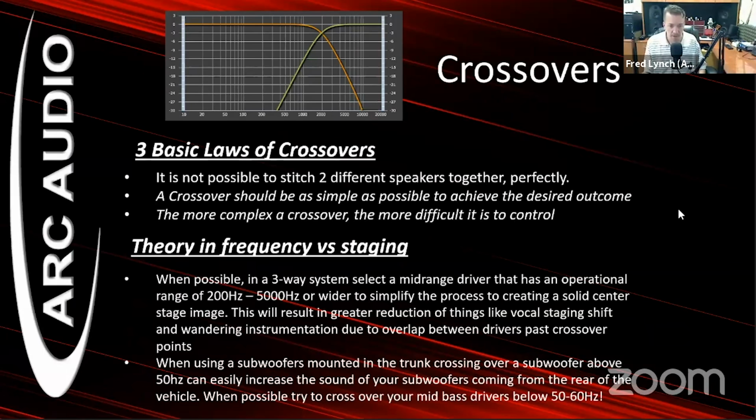And then when using a subwoofer mounted in the trunk, crossing over a subwoofer above 50 hertz can easily increase the sound of your subwoofers. A lot of people typically cross over a lot of those speakers at 85 hertz, 80 hertz. For street systems, you may be even louder. For an SQ system, you'll see a lot of people crossing them over well below 50 and 60 hertz, making sure that they have a great mid-bass driver up in the front, so that way they can try to couple everything at the front of the vehicle.